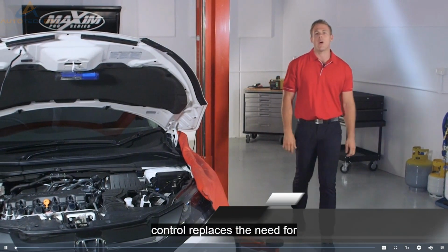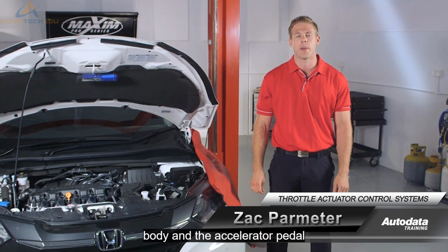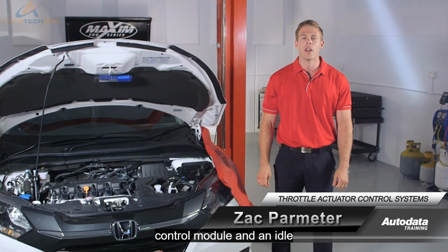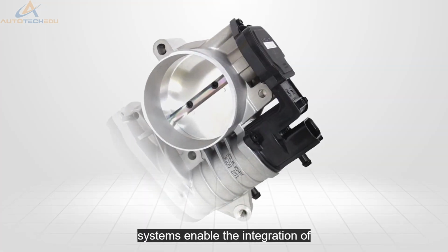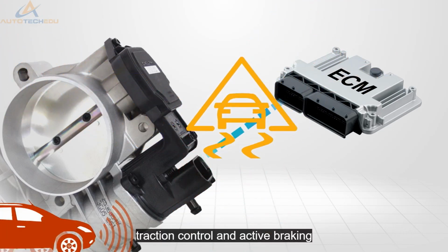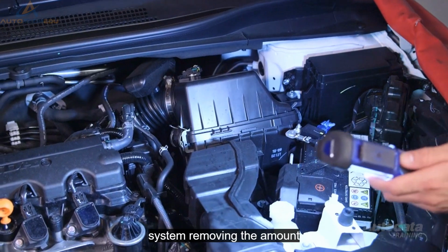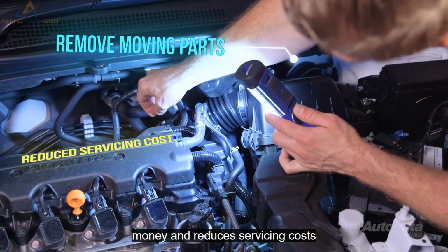The throttle actuator control replaces the need for mechanical linkage between the throttle body and the accelerator pedal. It also replaces the need for an external cruise control module and an idle air control valve. TAC systems enable the integration of adaptive cruise control, electronic stability control, traction control, and active braking control with the engine management system. Removing the amount of moving parts also saves money and reduces servicing costs.